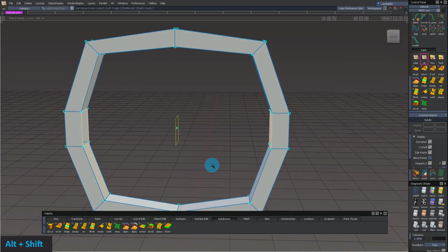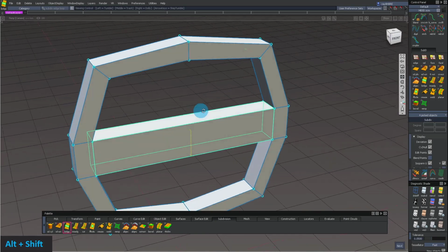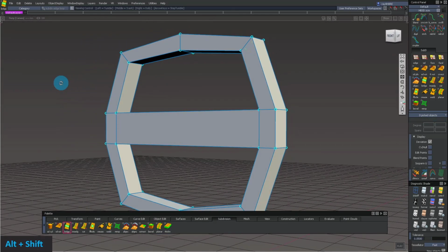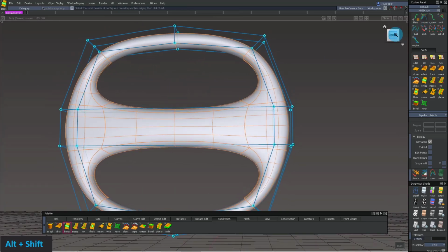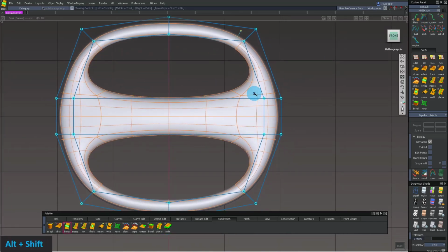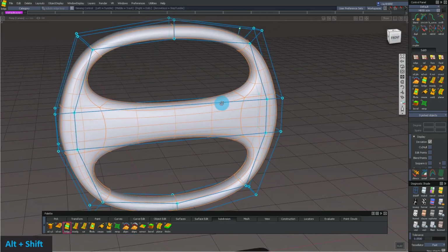This is one of the powerful aspects of Sub D modeling. You could do these really big movements and changes, and it's fairly quick and you get a result really quickly, right? So now that I have them bridged, if I shade them up, I'm using hardware shade here, and it's just hotkeyed up to my H tool. We can see that it's making the connections we want, but it's way too round. So I want to add more control there, right?